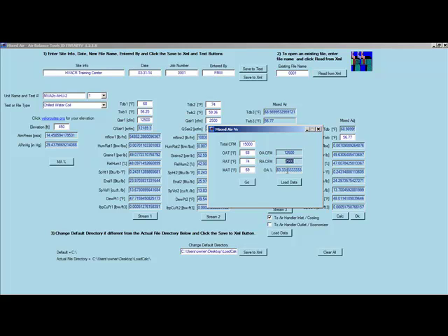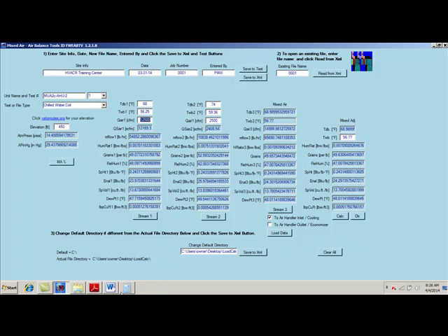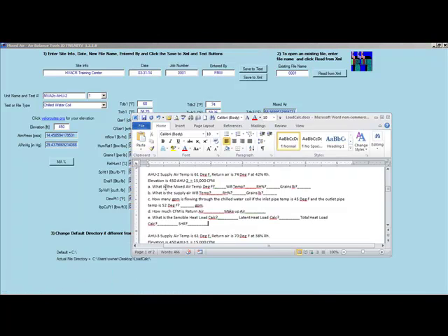So 83% of this is makeup air. And makeup air actually is coming from outside air. Do MUA2C. So now what we want to do is go ahead and say, what is our mixed air temperature, wet bulb, relative humidity, and grains of moisture.